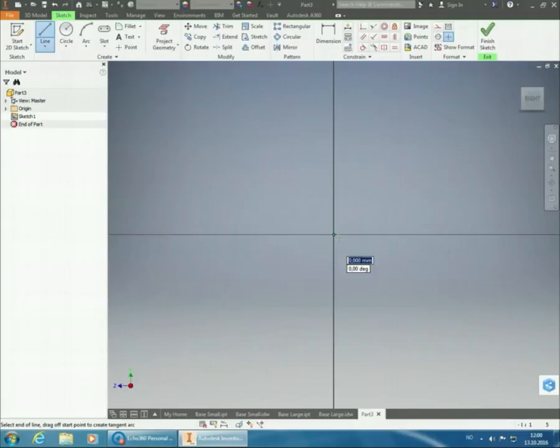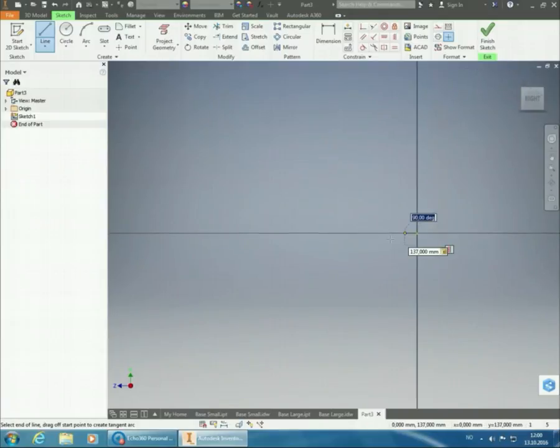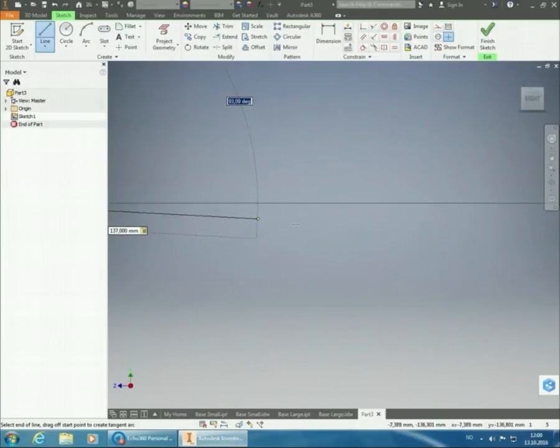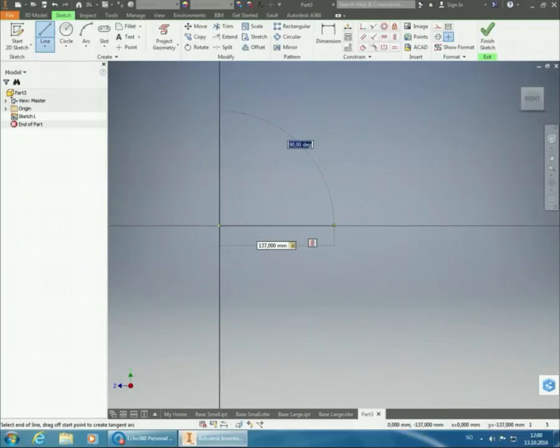So it doesn't really matter if we've got it completely centered or not. So I'll just start at the center point, and I'll move off 137 millimeters to the side, and just make sure that it becomes trapped into a horizontal line there. Gotta zoom out a bit to get it to constrain itself. So there I have it constrained horizontally.